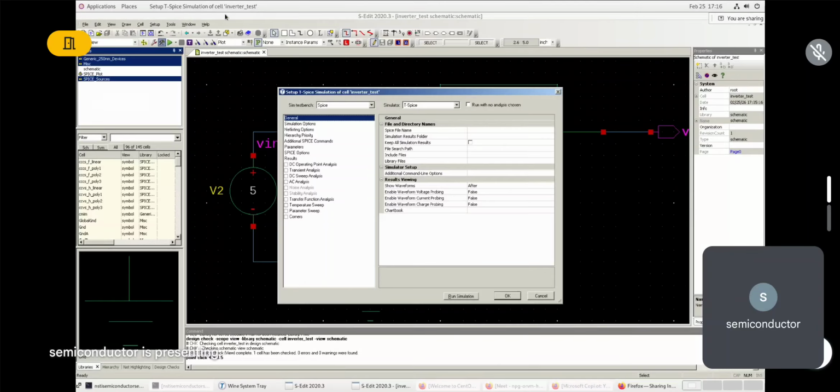As I told in the beginning, here we have to give the spice. Here we have analog path spice, that is AFS, ELDO and T-Spice. Complex designs use ELDO and basic simulation uses T-Spice. Very high end uses AFS, analog path simulation. And even for analog mixed signal, you will use the AFS.